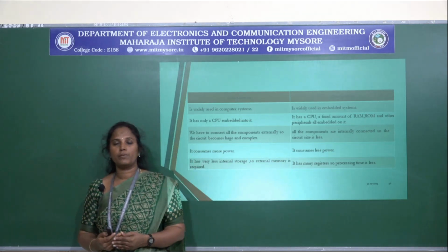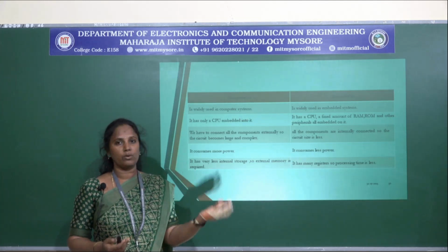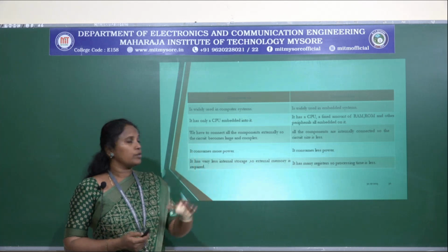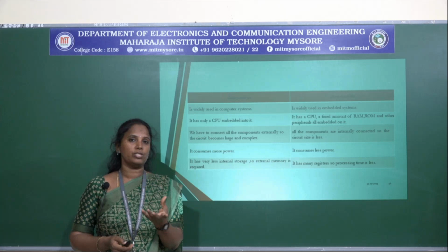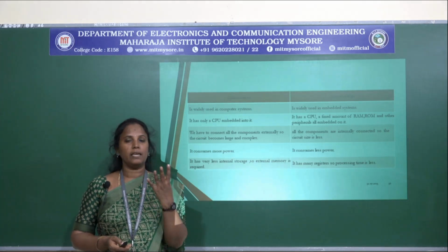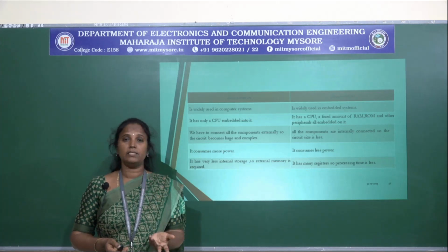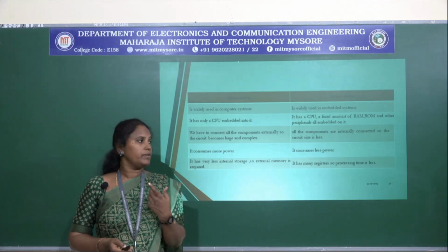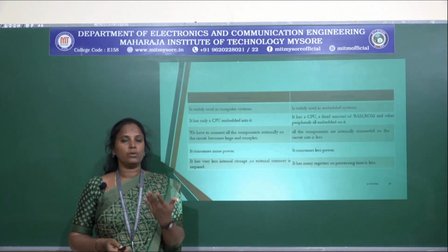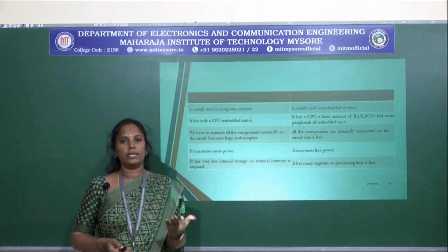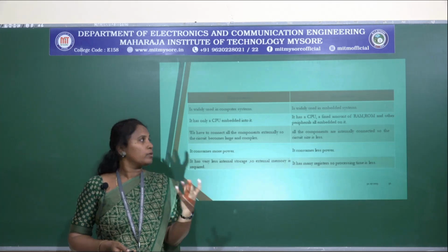So that's why your microprocessor has more complexity involved than your microcontroller. In the case of microcontroller, we have a system which is also called a system on chip, where it has inbuilt communication interface, interrupt, timer, then we have IO ports, and whatever we want, that is A to D and D to A converters, all these are inbuilt with respect to a microcontroller.